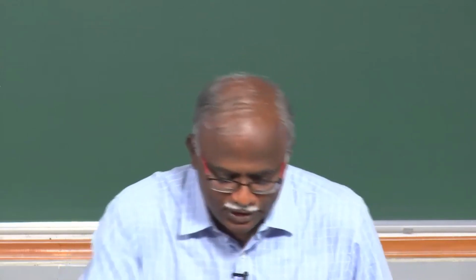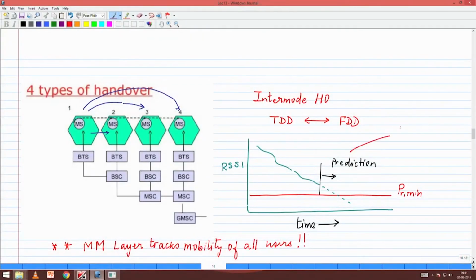So there is a signal processing technique called linear prediction. Those of you who work with speech know that looking at the past, you can actually predict some things in the future, what the signal will look like. So one of the things that you would want to use in this information is how fast the user is moving. So that would be a measure of Doppler, because that tells you how fast the signal will change. It also tells you what has been happening in the past. So one is Doppler, one is past information.